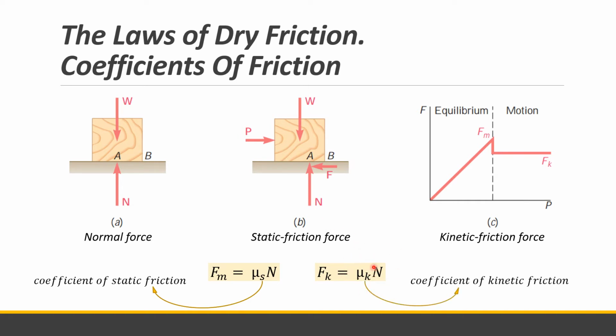So we have what is called the coefficient of kinetic friction. In our problems, this is a property of the material. Usually the coefficient of static friction and coefficient of kinetic friction are given. They are tabulated, but they are derived through experiments, so they were obtained experimentally, and there are available tables, or the problem will give the coefficients of friction for the specific problem.